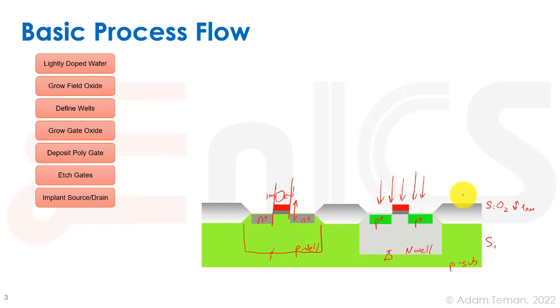And that's fine, because if it hits this area, it's going to get stuck in the oxide, in the field oxide. If it hits over here, it's going to be stuck inside the polygate. And actually, implanting some ions into the polygate is used to set the threshold voltage a bit better. So that's often used. They can also be covered, but it doesn't matter if they're perfectly covered, because in any case, the stack of the poly and the oxide is going to protect our channel from getting these impurities, which would really ruin it. It could ruin our transistor.